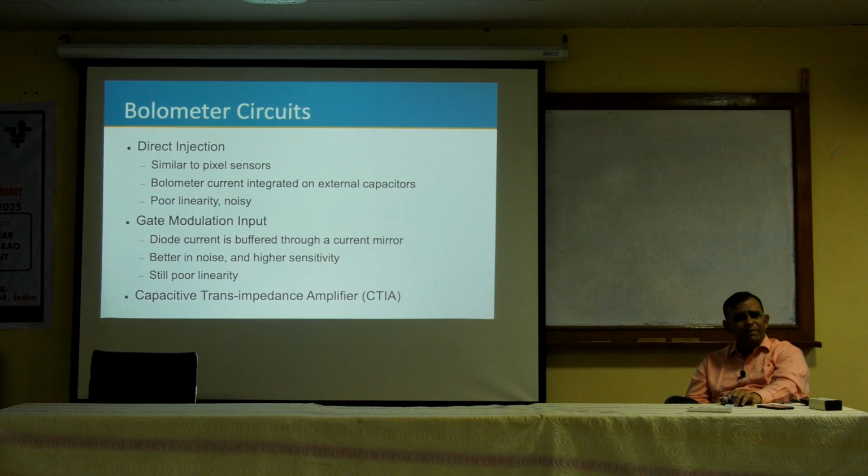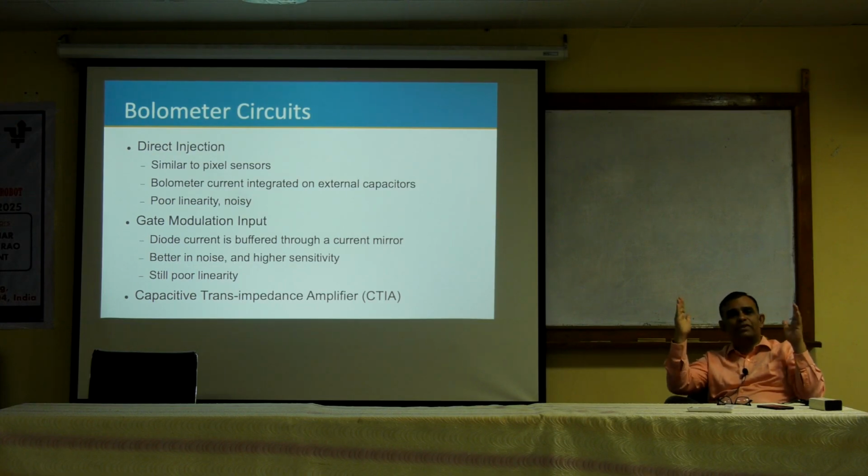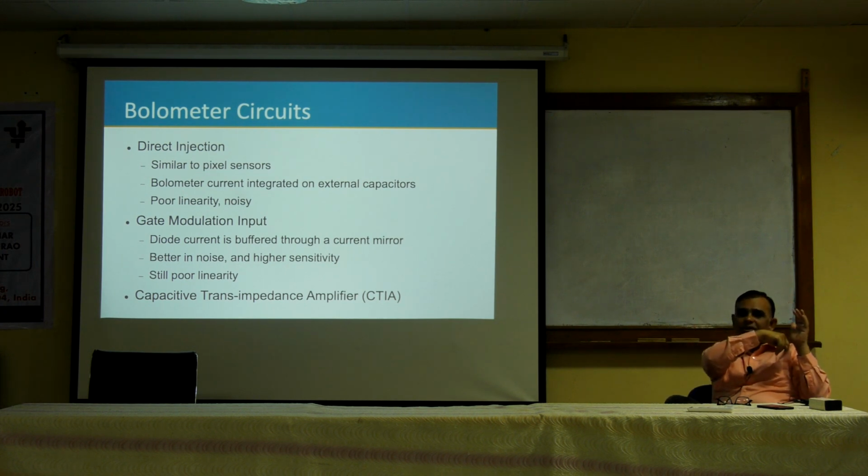Such devices can be made. They have been seen to have poor linearity and they are a bit noisy. They're a bit noisy because the capacitance you have now comes in parallel with my bolometer, so whatever I am integrating is also affecting the bolometer operation.